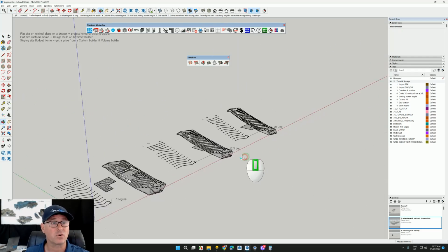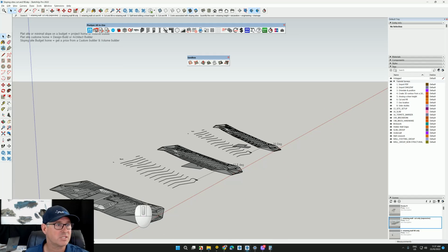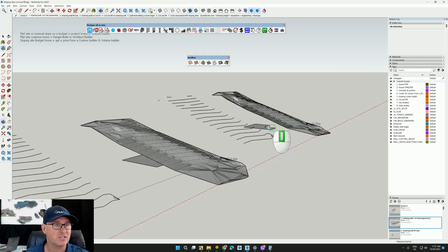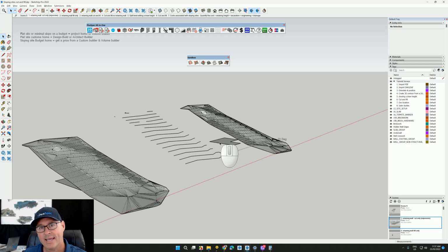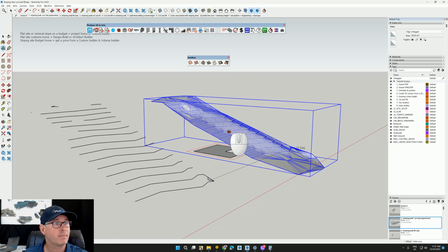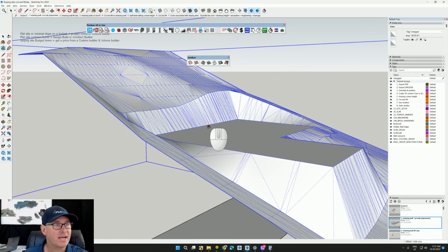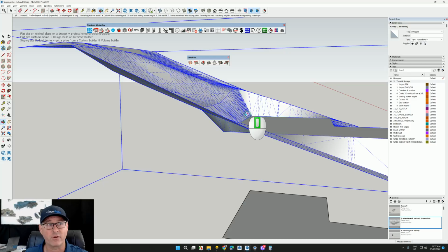Now guys, I quickly wanted to talk about one more thing here: we have two different sloping sides. The first one was 7.5, this is 12.5, and this is 20 degrees. Sometimes you have to draw the line and say it is not feasible to fill a site, and this is going to be a good example right here. If I select this and use my sandbox and stamp it, the height of my retaining wall and the engineering associated with creating such a retaining wall would be very prohibitive.